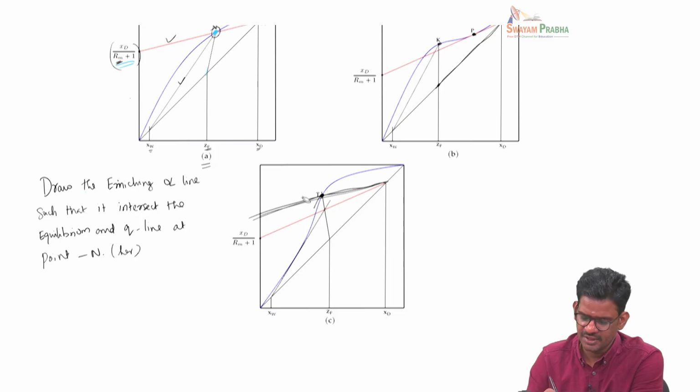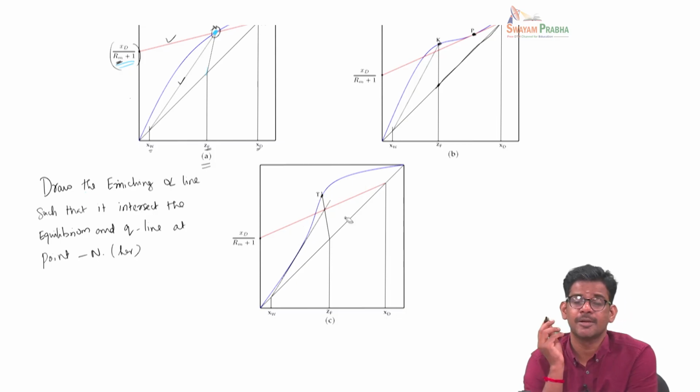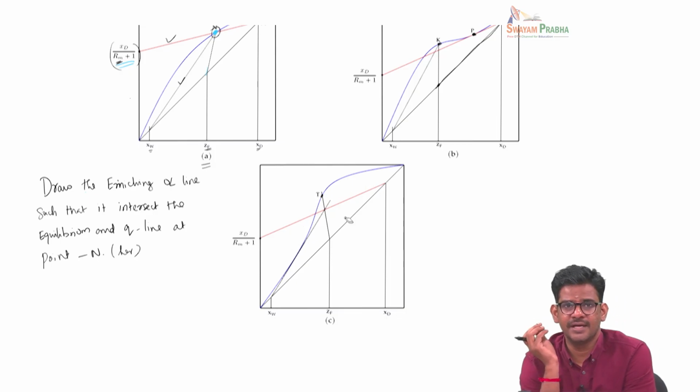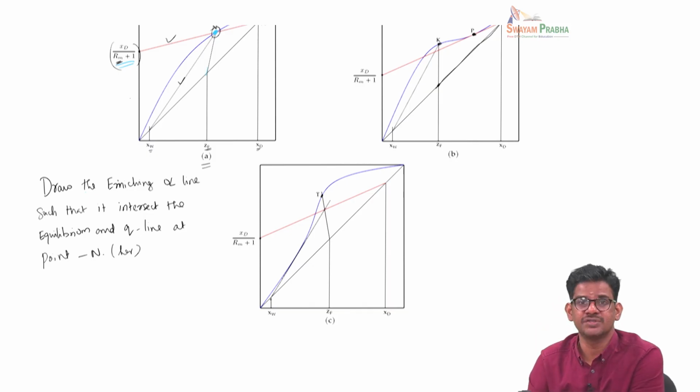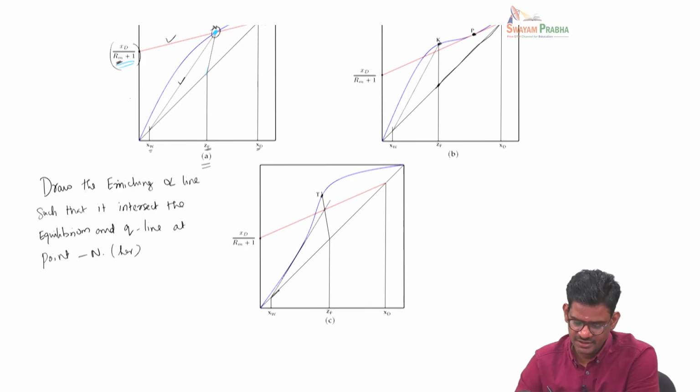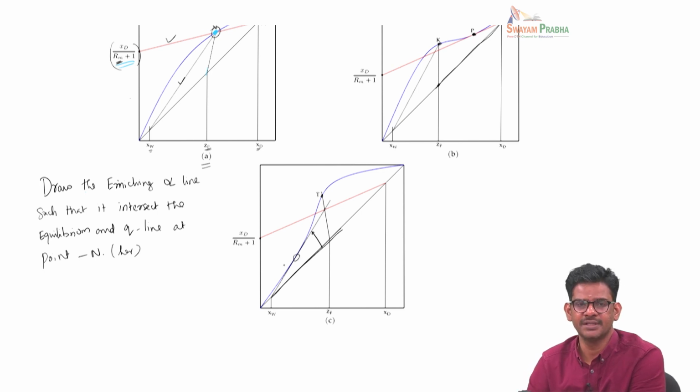So here in this particular case, the minimum reflux ratio has to be obtained from the exhausting line. So here we start with the exhausting line at the 45-degree line, and then we keep on increasing the slope all the way here where it just barely touches the equilibrium line at this particular point.